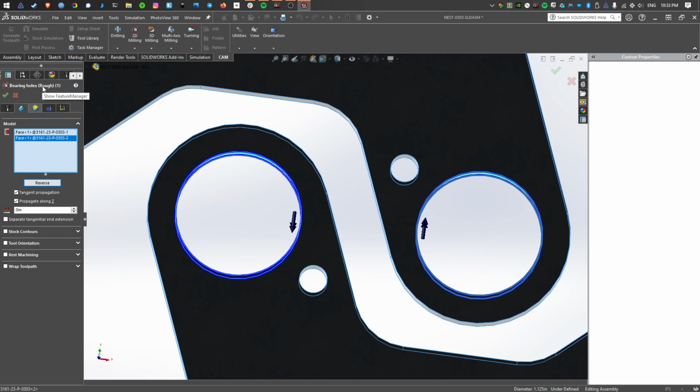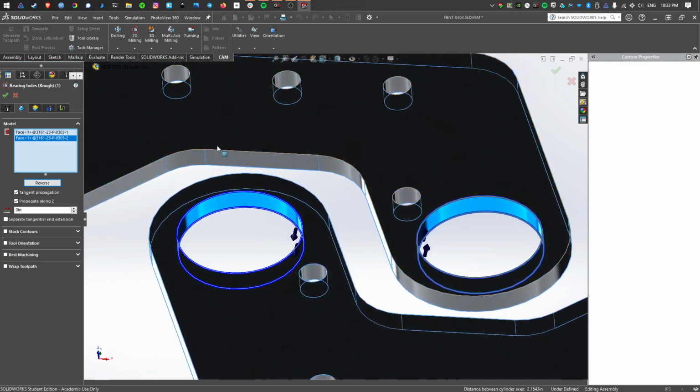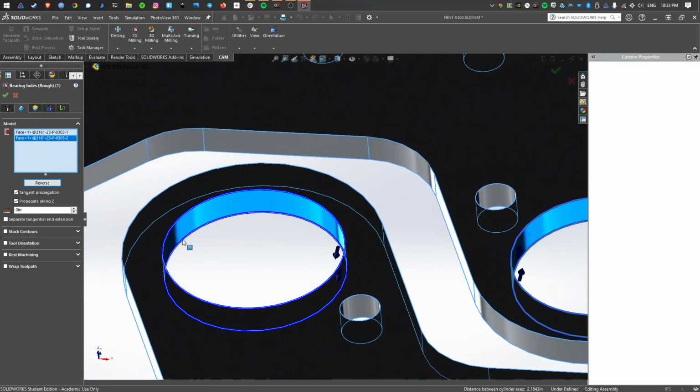Now this toolpath template has stock to leave turned on, so it'll leave 0.08 of an inch, and then you need to do another toolpath for a finishing pass, which will remove the 0.08 and finish it to the true dimension.